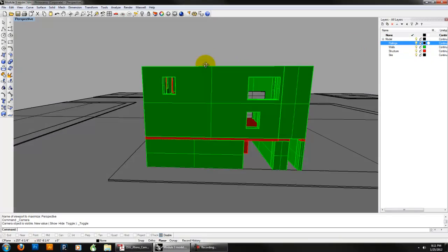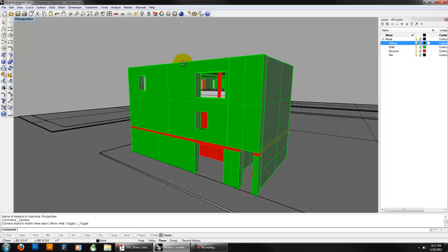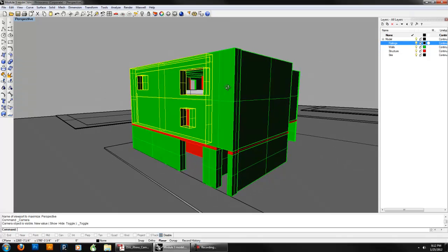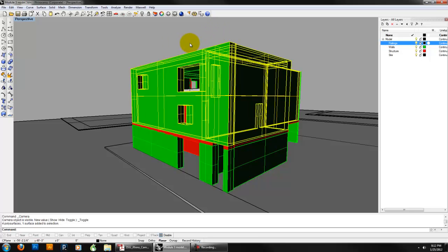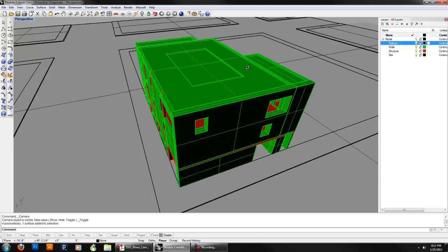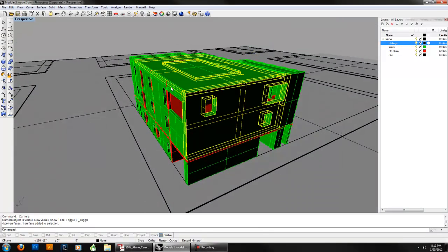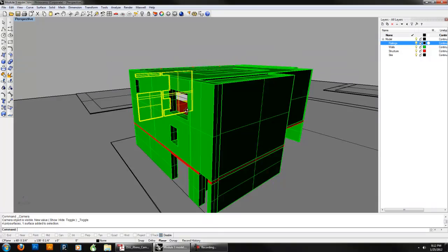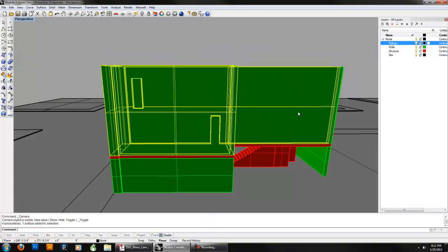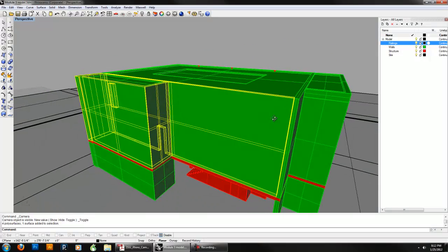Another thing you can do is you can choose specific objects with the mouse. You can actually use your mouse to click them, or you can make a window and pick them. If you want to add to a selection, you hold down Shift. And sometimes when you choose something that's near something else, you get a pop-up window and it allows you to choose the thing you want to choose. Okay. To remove from a selection, hold down Control and click, and that will take away something. Okay. You can choose some selections, right? And you do different things to them.